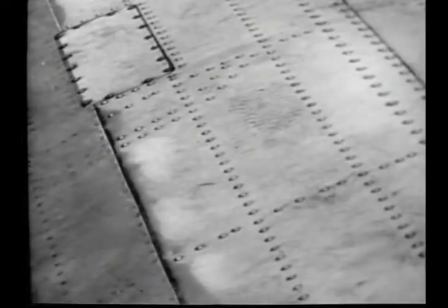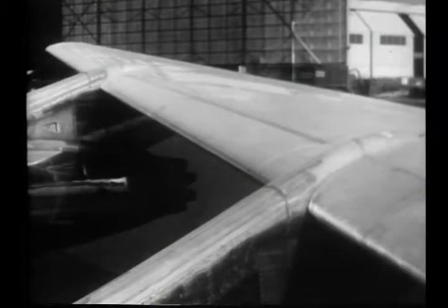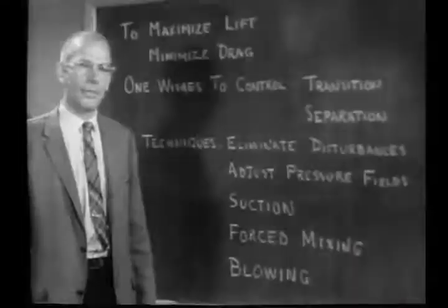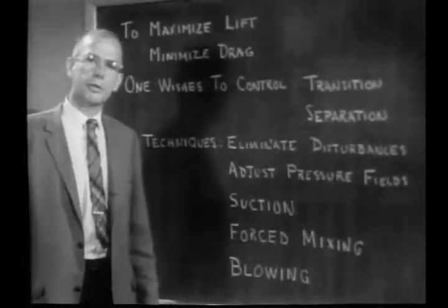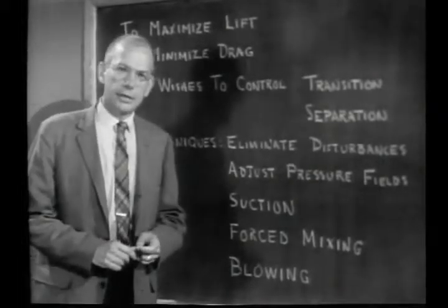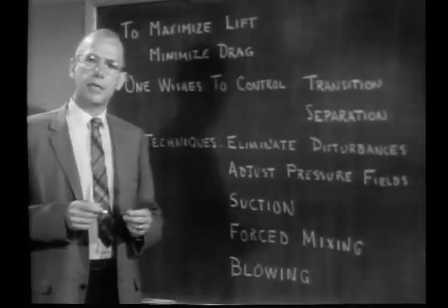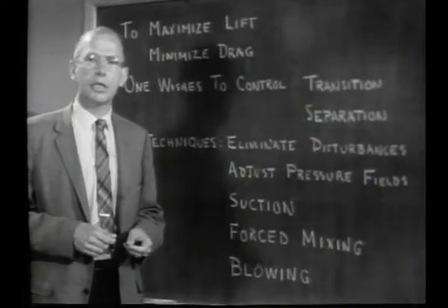The designer has learned to control some of these factors. Disturbances arising from rough surfaces can be reduced. Other disturbances, such as noise, vibration, or airstream turbulence, can sometimes be avoided or isolated. Designers have also learned to use the strong influence of the pressure gradient on the stability of the laminar boundary layer. That is, its ability to damp out disturbances.